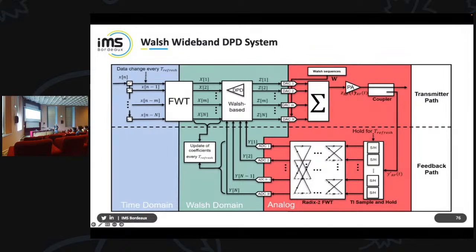That's why I was talking about billions of inputs. But normally the convergence is 10 times faster, so you can sweep and learn a lot. Most of the time now, your PA is just trained for a very narrow band and few combinations. The idea is to have 20 GHz wide band compensated with all the possibilities, any kind of modulation. As I said, you also take time into account: what happened before can affect what will happen after. Much more complexity.